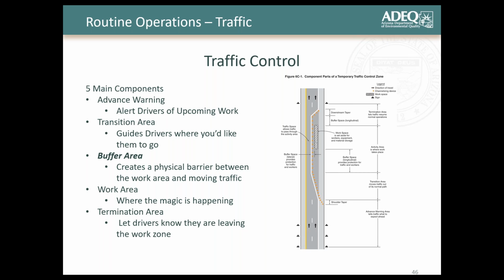And I realize, especially since a lot of those folks doing the sewer line cleaning or CCTV inspections are in very fast moving traffic control operations, sometimes folks get really comfortable with the buffer area, especially based on the amount of space that you guys have out in traffic. So give yourself as much buffer as you possibly can, right?